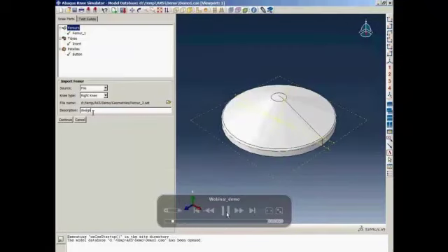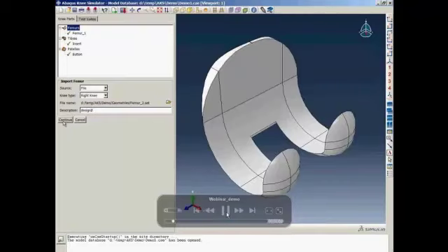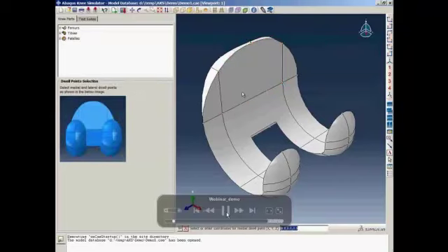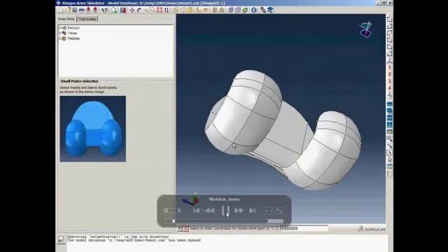The user can give a description of the components imported. Next, the knee simulator asks for a few landmarks on the implant components. So for each implant during import, different landmarks are requested. These landmarks are needed for both meshing the components and also aligning the components in the assembly. First is the plane on the femur components. Next, we ask for the 2 dwell points on the femur components.